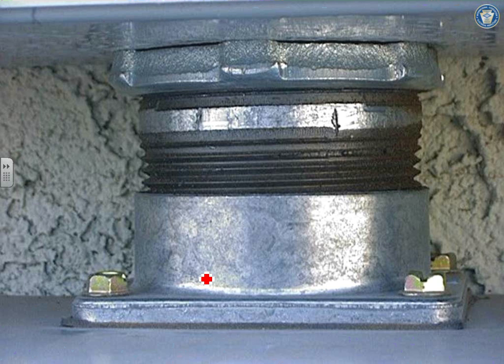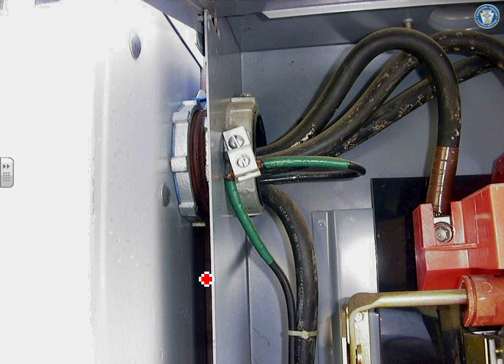So this is your supply side bonding jumper. You're bonding the conduit into the box. Conduit into the box, so that's the only way. This is your bonding bushing here. This conductor right now here is your supply side bonding conductor. So if you're in doubt and you have a bonding bushing like this and you bond the conduit, you solve almost all the situations, bonding the conduit at the service or anywhere else. All the other alternatives, guys, are there to give you a cheaper alternative to having a bonding bushing, really.